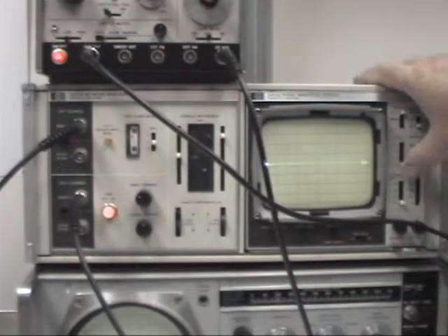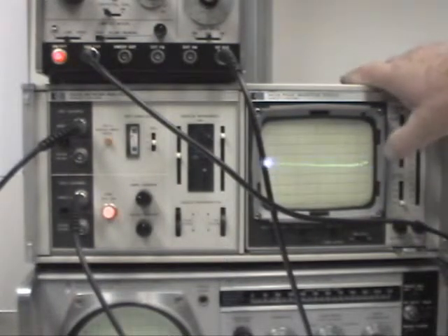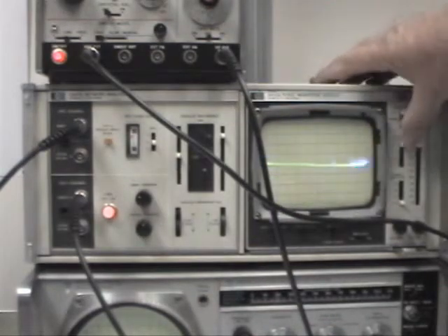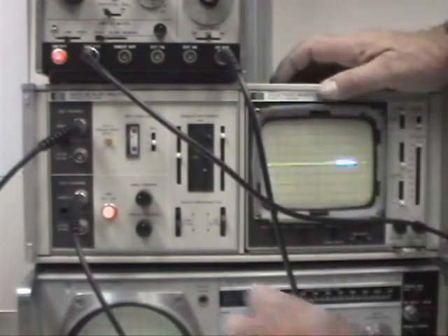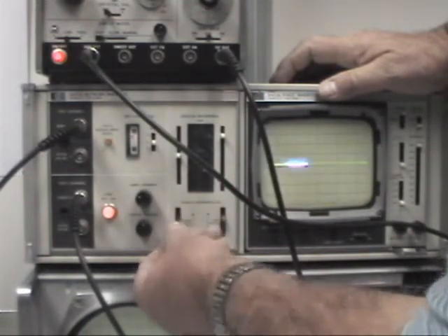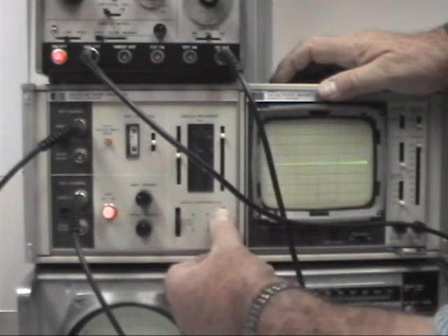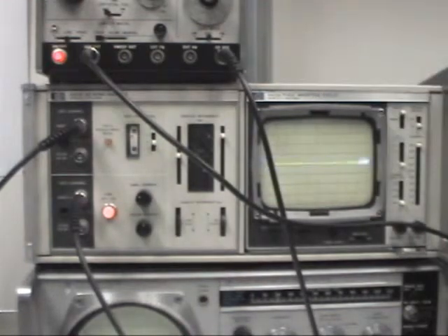Now if I were to go to a full sweep, we start to see a little bit of the imbalance in the cables and the rest of the system, but not a whole lot. We're just off maybe a 1/10 of a dB right here. So we're all set. This is going to be our 0 dB setting. We have a dial showing -20 and -3. We'll set that to where it shows 0 dB. And now we're ready to measure something.